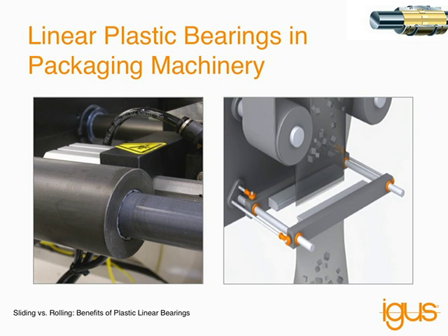One absolutely core industry for plastic composite bearings is packaging, the packaging machinery business. A lot of applications. One of the classic ones would be the welding jaws on vertical form fill seal machines. These are basically machines that have a hopper above that might dispense chips into a bag, and these welding bars or welding jaws are the parts that close, usually through heat.